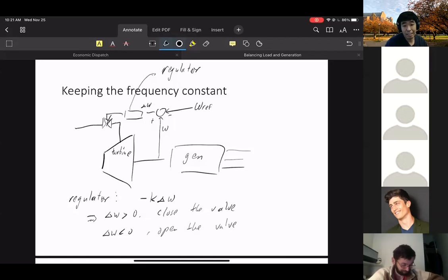So this is basically a droop, right? For the people who work in submarines and ships, this is called a regulator with droop. This K is a droop constant. As a negative feedback controller, droop means as the frequency changes, the power will change. This is used quite often in a lot of systems. Okay.